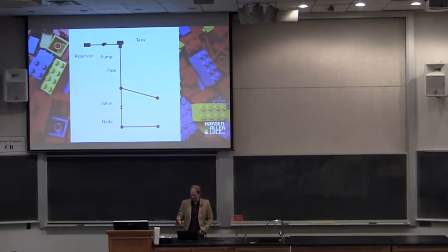Hydraulic models are similar. You just have these 6 components, but with these 6 components, we can put together a model of any water system in the world. That's all you need, are these 6 components. A reservoir, a pump, a tank, a pipe, a valve, a node. You put them together in the right order and give them the right parameters.